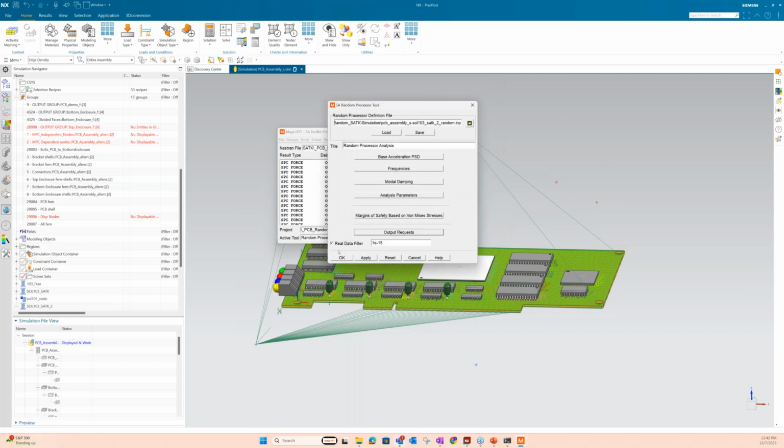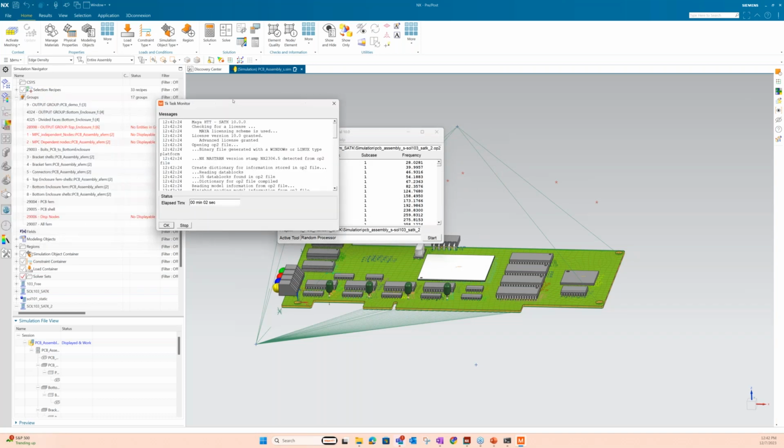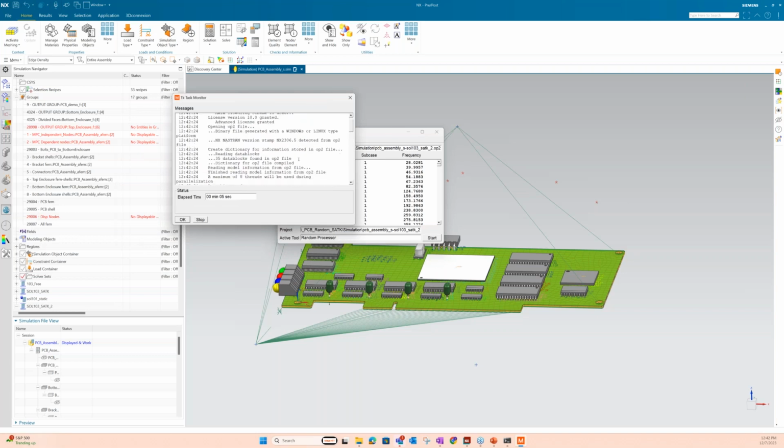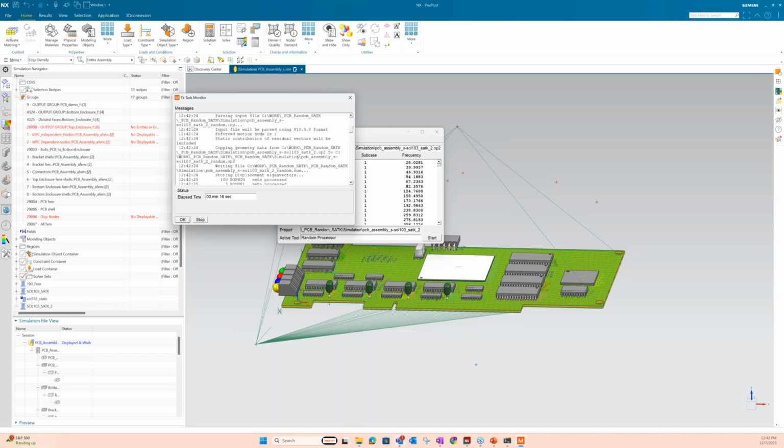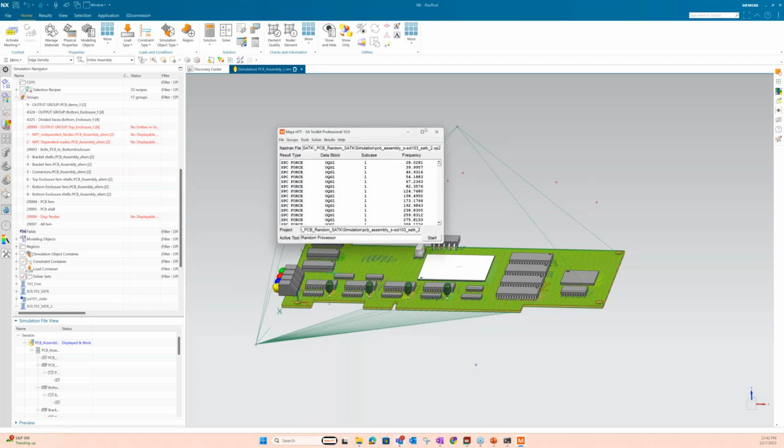So we'll click OK, click OK on that, and then we'll go ahead and hit start. It'll run here. I created quite a few results, but this one's going to be pretty quick. Just a couple more seconds, I think. I did request a lot of stresses though. Oh, there we go. We're done. It took about 18 seconds. I requested a lot of results. It's also a small model, but you saw before, a 160,000 degree of freedom model solves in seconds as well.